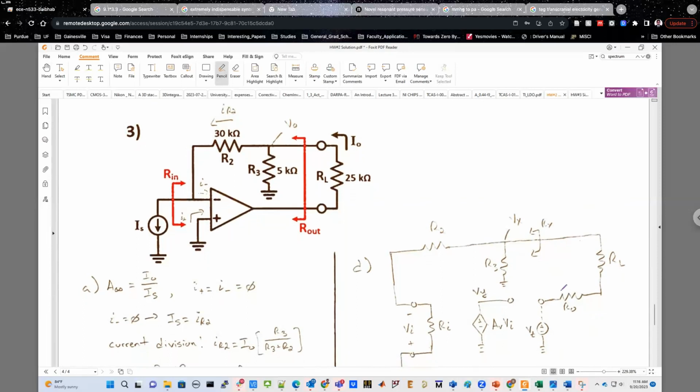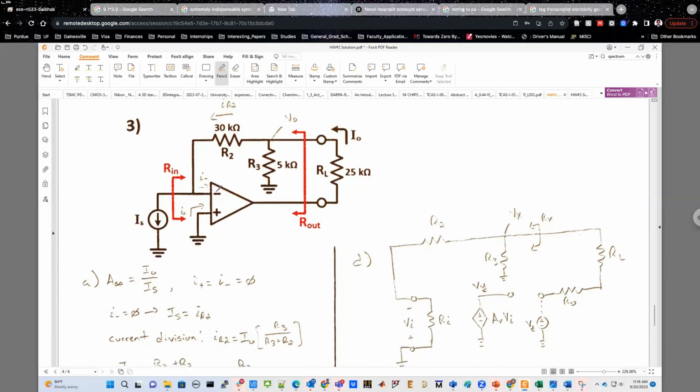Now, to do that, you can use both the approaches related to voltage domain or current domain. You can assume that the op-amp, because it was given in the problem, right, that the voltage gain of the op-amp was maybe 400 or 500. So you know from there that at the output of the op-amp, you have this dependent voltage source. If you have a dependent voltage source, you'll have a series resistance to it, and you can find out what the feedback path gain, beta, is, assuming that this is the dependent voltage source. In that case, beta will be the voltage developed across Rin, divided by the voltage available at the output of the dependent voltage source. So your beta will be a voltage over voltage quantity.